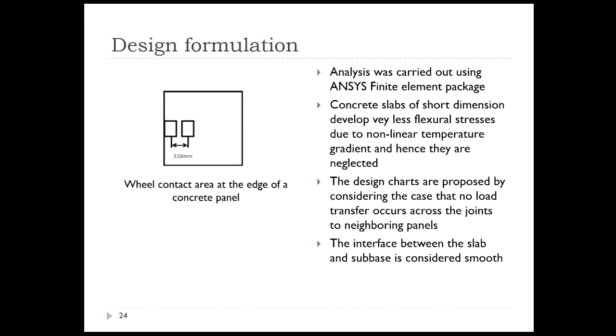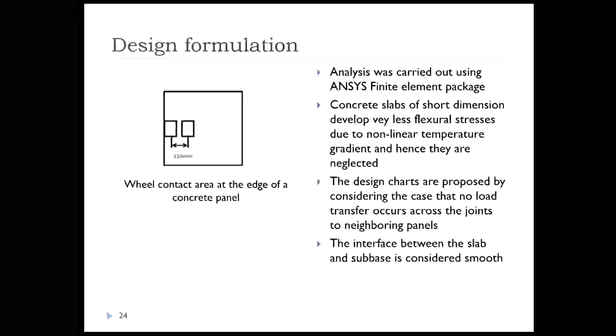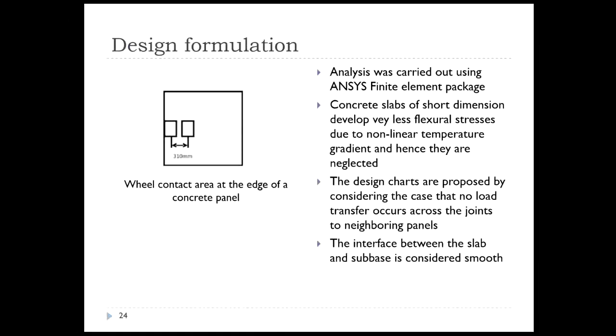Once we determine our K values, the design charts proposed in this paper were given considering the flexural stresses along the edge. Basically, these panels are very small. These panels have a size of 0.5 meters by 0.5 meters, and the largest panel they consider is a 2 by 2 meter panel.